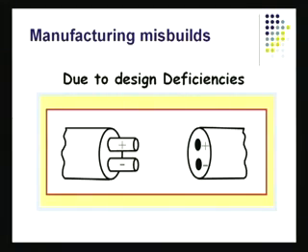If there's a weakness in the design itself, if the design of the cover is not good enough, I'll probably have a problem there. I'm showing you an example here, which is a design defect. Look at the two parts of it. These are parts that are supposed to fit together. Now this is a polar connection. Polar means there is a positive end that must go into the positive hole, and a negative end that must go into the negative hole. If they're of equal size, you know and I know that there's every chance that someone is going to connect it backward, connect the plus to the minus and the minus to the plus, if the design is like this.